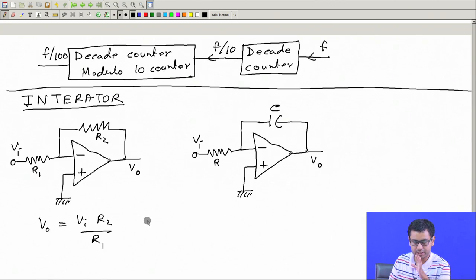Now, I will just give you a way to remember this circuit. You just note that in the Laplace domain, if you have studied that in any other course, we can write the impedance of a capacitor as 1 over Cs. The impedance of an inductor is Ls, capacitor is 1 over Cs, R is R. That is what you might have studied.